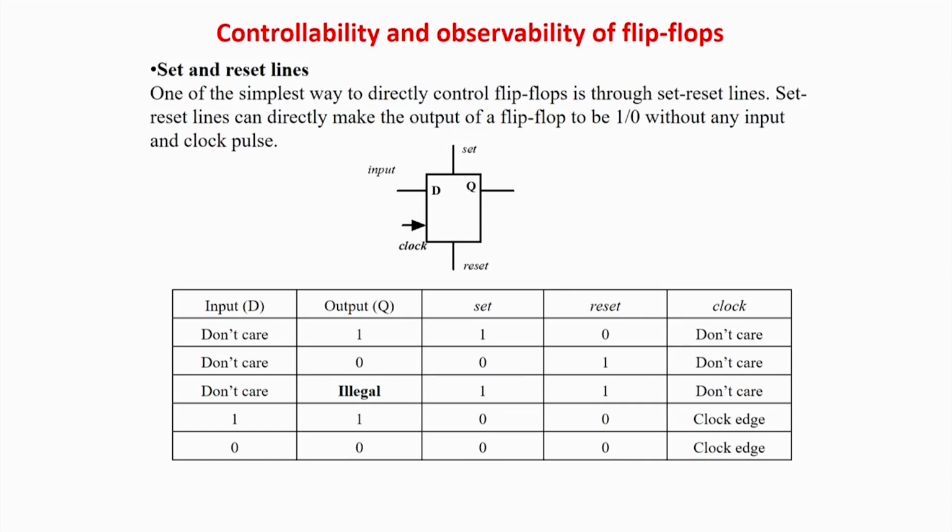So we require that our complexity should not grow more than the complexity of testing a combinational circuit. Combinational circuit testing, what we have seen, that even if there are 2n stuck-at faults, the number of test patterns will be much less than that, because one test pattern will cover multiple faults. And not only that, basically for one fault, maximum one test pattern is required. That is the worst case. But in this case, as you can see, the things have started blowing up. So how to do it?